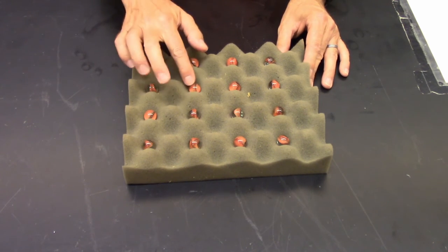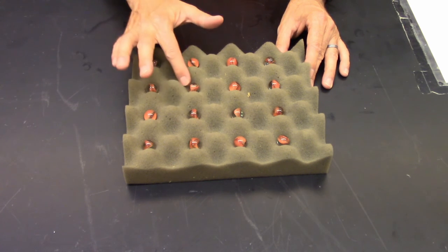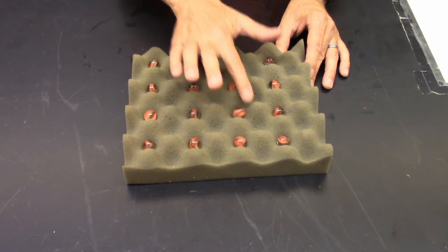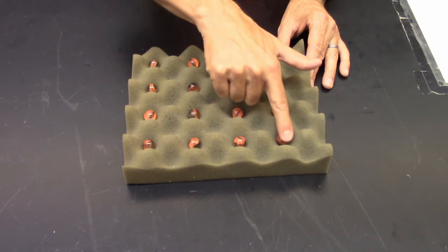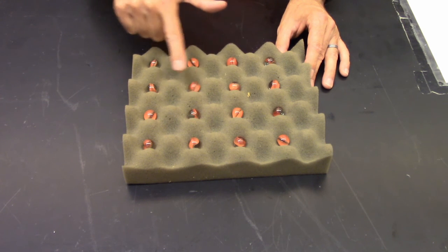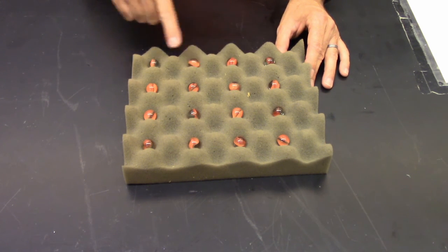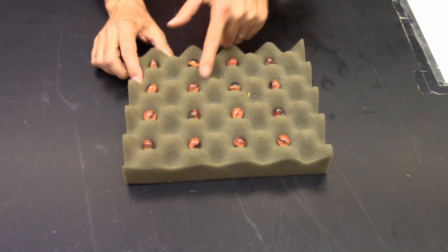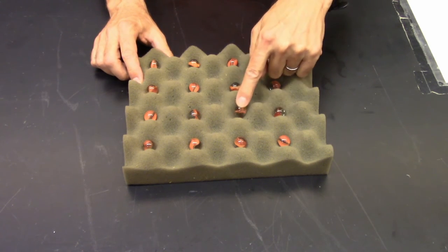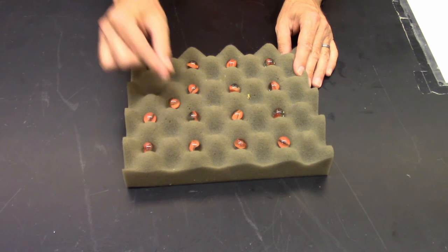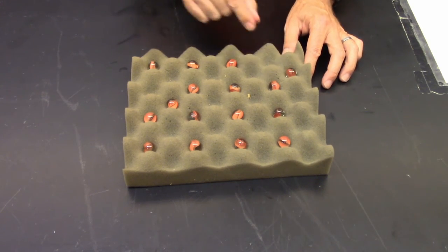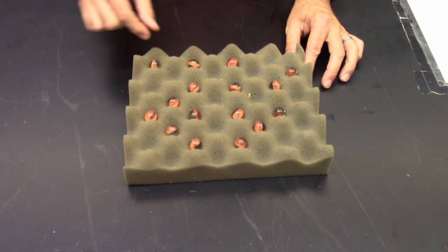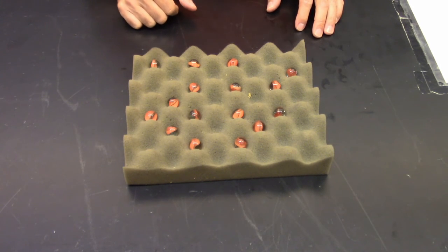And one way to model that is to say, if I move each atom just a short distance from its normal home, then it will go back. So I can move each atom within the array, within the lattice, just a little bit. If I don't move it too far, then the elastic nature of the material, which we'll study more when we start to talk about materials out of which architectural structures are built, these forces will bring the atom back to its initial position. But if I push it too far, then it deforms into some other location. And I could do this in a way that's maybe a little bit different for the different atoms of the solid. And now I've deformed this solid in an incoherent way. And this is an irreversible interaction.